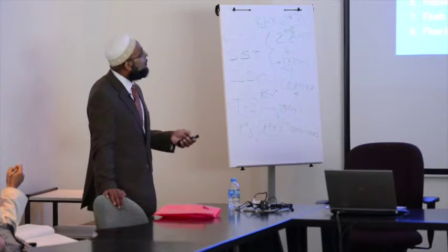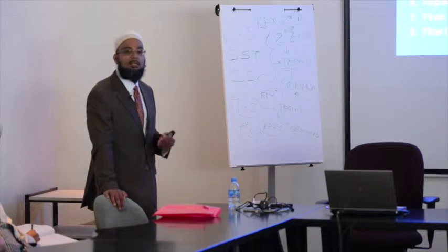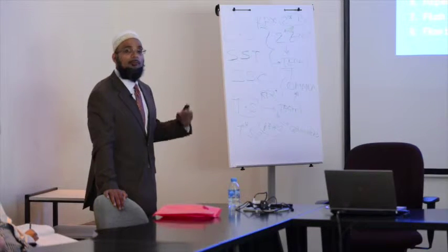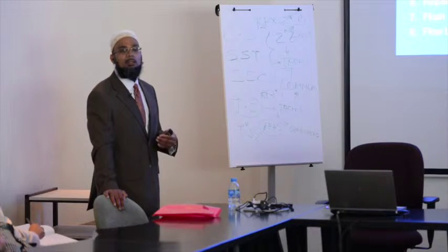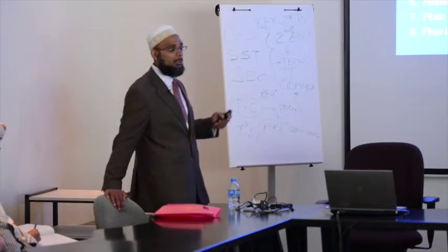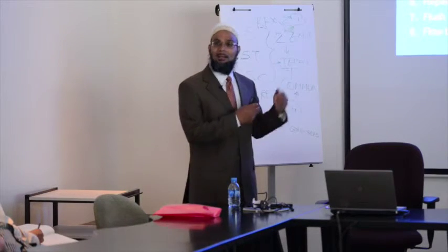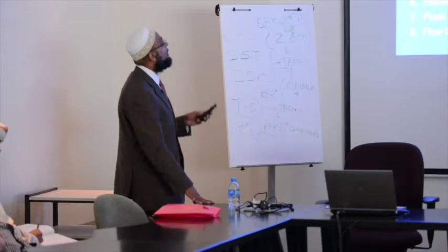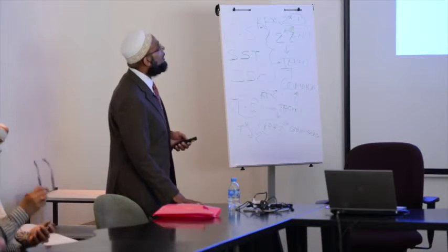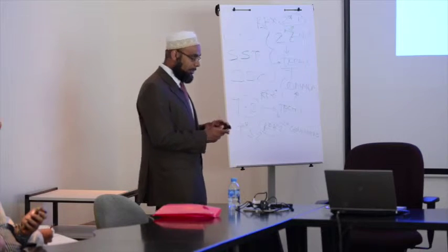After that, we flush to the top of perforations. We don't want to leave live acid in the tubing. Then we flow back, or if it's a water well, water injector, we continue with the injection, right? So this is the sequence, and looking at that, we say, okay, what can go wrong? I mean, it almost looks like a cookie cutter kind of design. So what it hides are some of these challenges that I've listed over here.